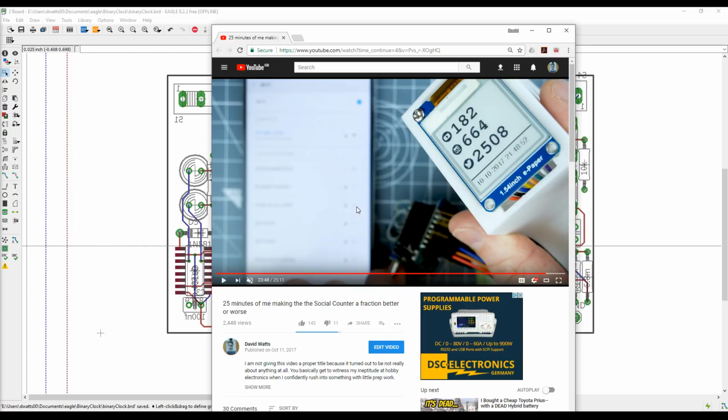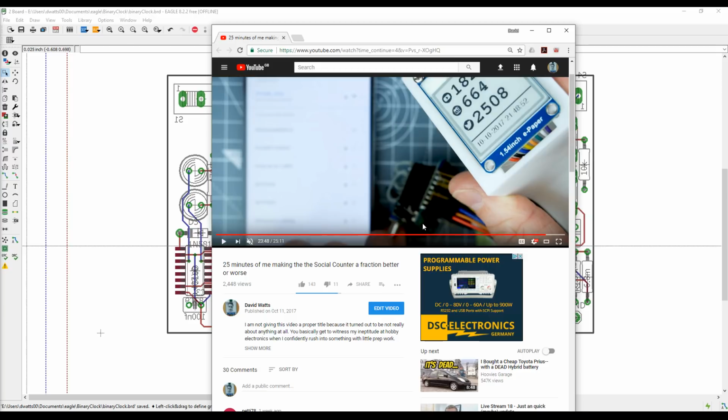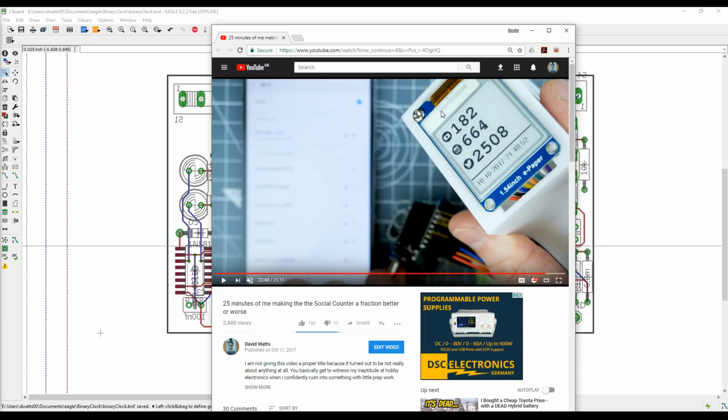So I decided that it probably wasn't best to be using batteries when the CH340G, which is the USB comms chip on the board, the USB to UART or whatever it might be, I can't remember. But essentially it's my USB serial comms. And it was sucking up so much power. But in reality, it was probably only sucking up like 4 milliamps, or maybe even less than that. But it destroyed these batteries, which probably had a capacity of around 800 milliamps. It ruined those batteries in a week. And so it didn't work.